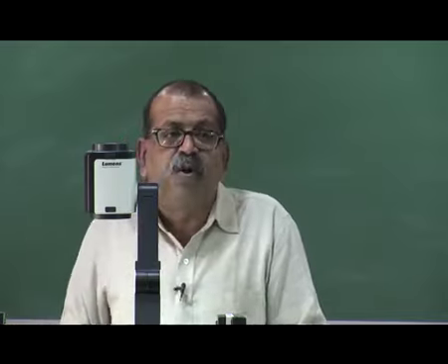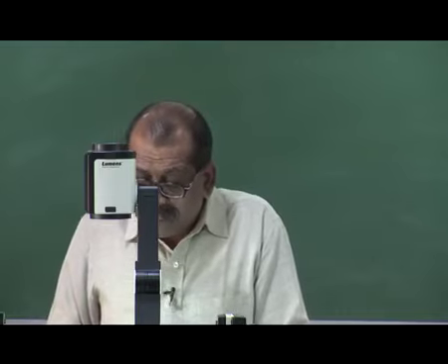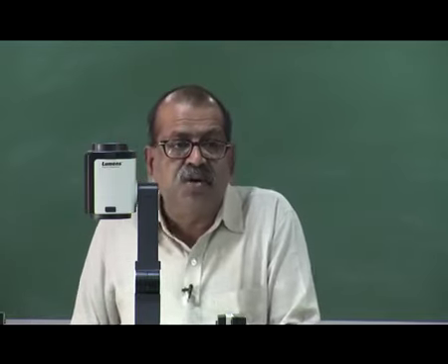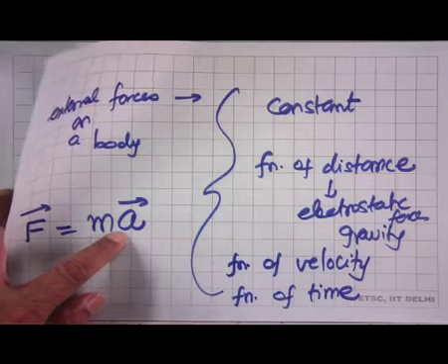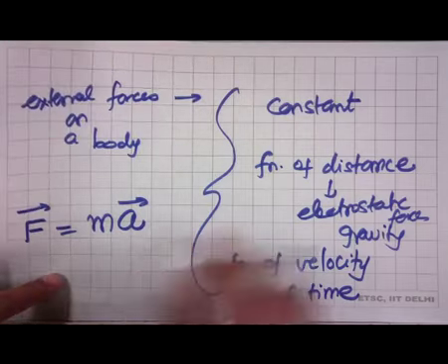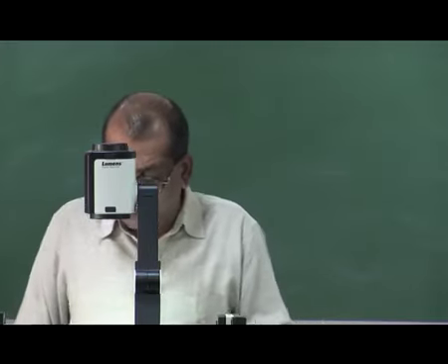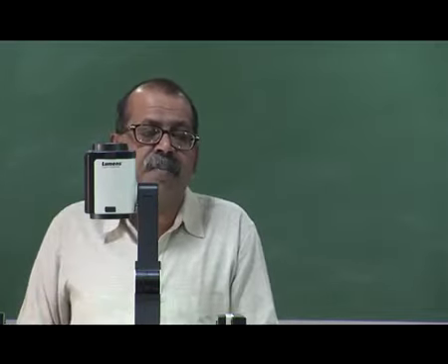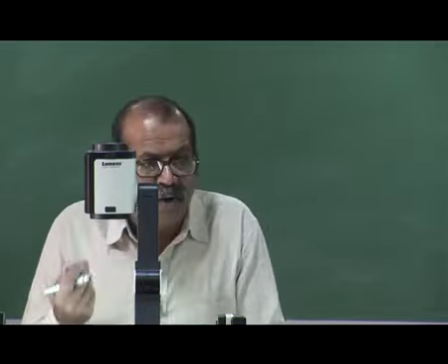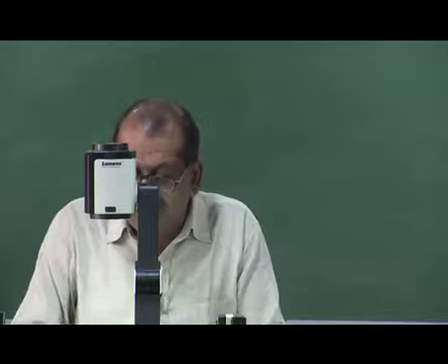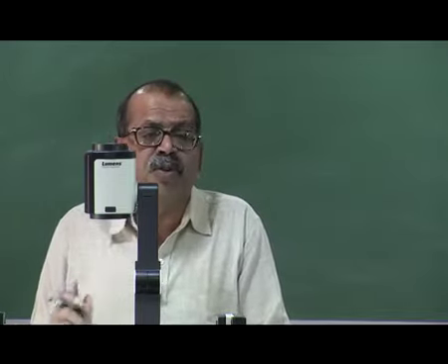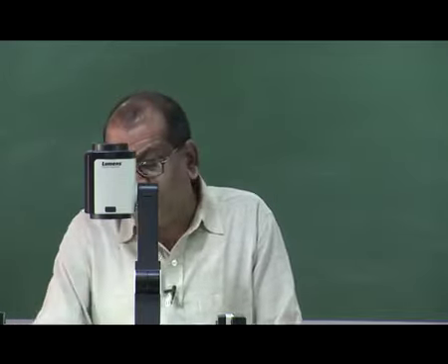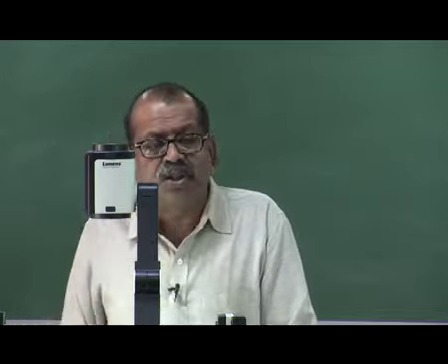What we will also see is when force is a function of velocity, then we will write this acceleration as dv by dt or v dv by ds, and then split the two parts. When force is a function of distance, then as we will see in the next chapter, we will develop work energy methods for solving the problem, and they often offer a convenient way of solving the problem when force is a function of distance. And when force is constant, we could use either the work energy method or the impulse method to solve the problem.